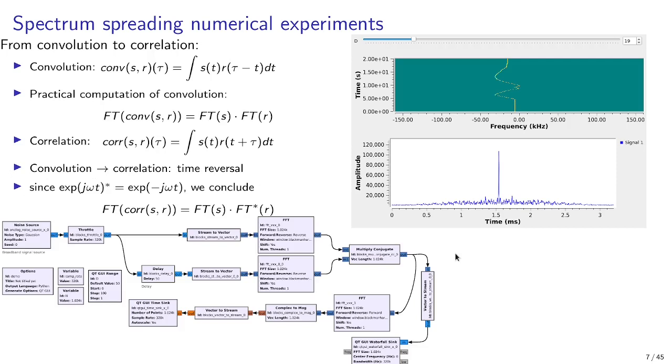So these are implemented using GNU Radio for prototyping. However, GNU Radio will not provide the correlation block. So we need to relate the convolution and the correlation to the Fourier domain. Indeed, all these quantities are integrals over a number of samples, and if we replace the integral with a sum, we see that the correlation multiplies each signal sample with a pattern time shifted. The objective is to find at which tau time offset the pattern is detected in the noisy signal.